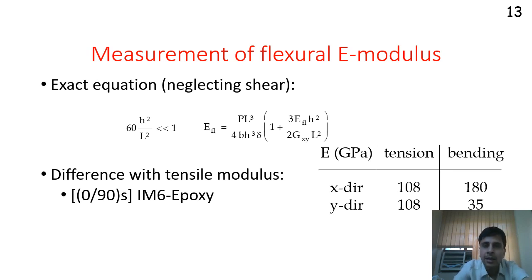However, the flexural modulus in the x direction and in the y direction is going to be much different. First of all, the flexural modulus is higher than the tensile modulus in the x direction and significantly lower in the y direction. Can you guess why? Hint is, think about the D matrix.